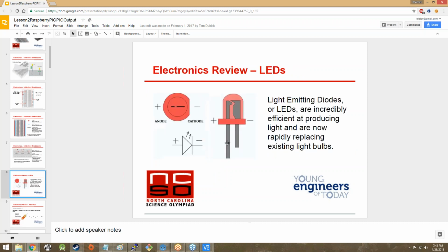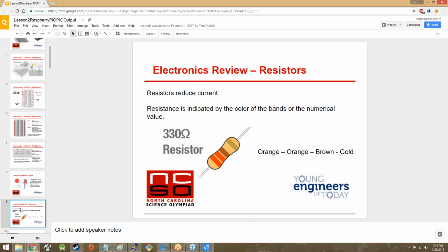things like LEDs can kind of pop open. They can get really hot, and then it can cause the air inside of the little plastic bit of the LED to expand so much that the plastic bit explodes. And thus you get little dramatic LED pops. So by putting in a resistor, you can keep the electricity from going through too quickly, from heating up too much, and consequently, you can keep delicate electronics from becoming too hot and doing something like breaking.